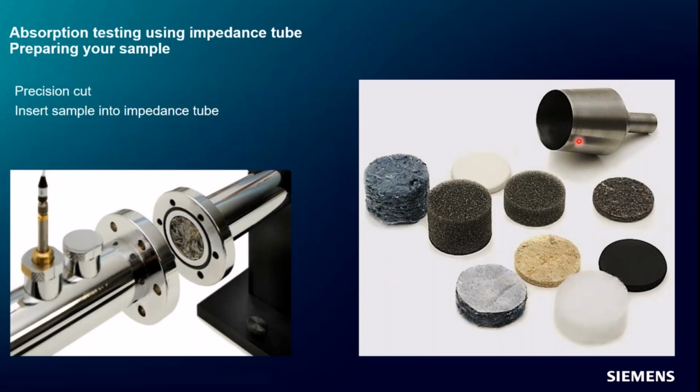You put it in a drill press or something like that, and it spins around, and this edge right here is really sharp, and it's engineered to be exactly the same diameter as the impedance tube that we sell. And so you can cut your own samples of foam or carpet or whatever it is that you have. Some places who do this for a living, like material manufacturers and that sort of thing, will actually have laser cut foam and material so that it's very, very precise and very, very repeatable.